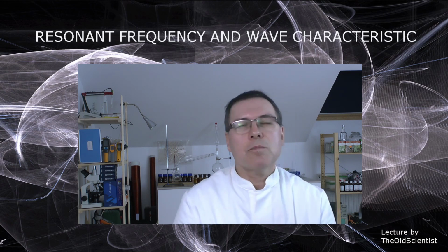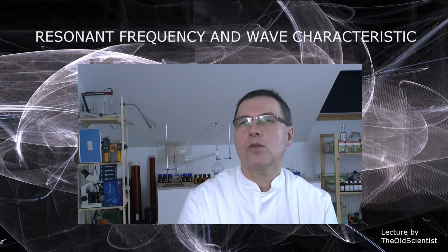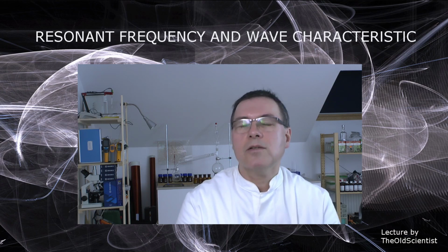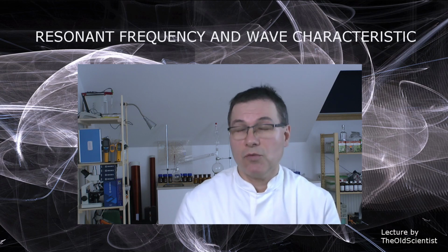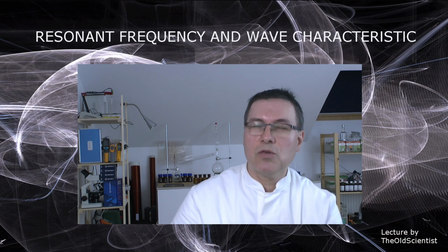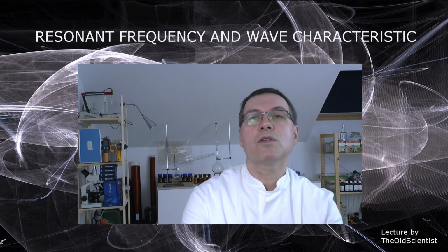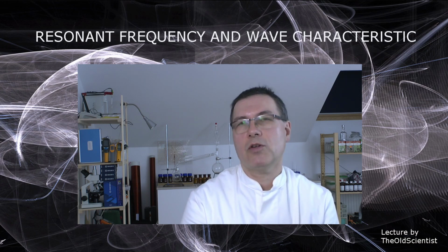The crystallization, because of the way the materials are hanging together, they create a bonding. And this bonding is, of course, allowing current to flow in a special direction, but it creates also resistance. And the issue is the resistance. The crystal itself is not so much the issue. It still gives you the opportunity to have a strong magnetic field saturated in this core material.